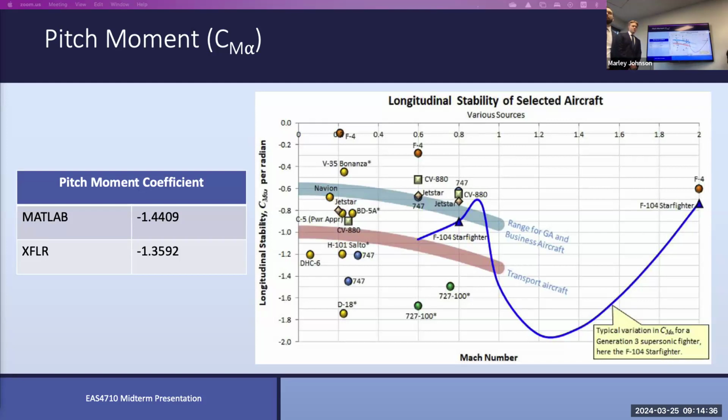Okay, understood. In addition, we also wrote, within MATLAB, the lifting line theory, and applied it for the calculations, including an efficiency factor which we also plug into the other calculations. That's how we optimize, for example, aspect ratio and all that. I think we added around 50 different elements to our lifting line theory.